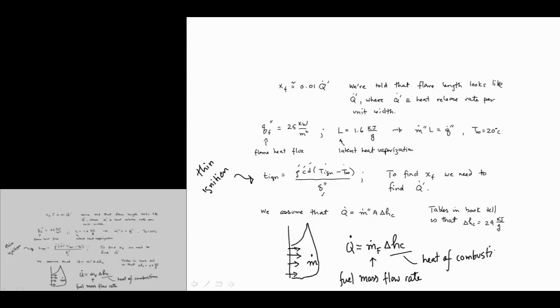And so for some of the types of pyrolysis gases that you liberate from solid combustion, we have things like 24 kilojoule per gram for the heat of combustion. So like cellulosic materials and a lot of polymers. Cellulosic materials are actually closer to 16 to 18.